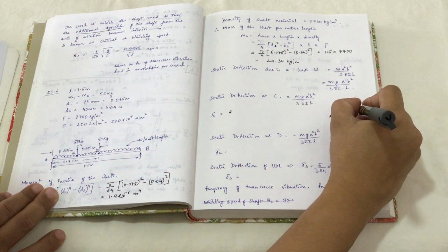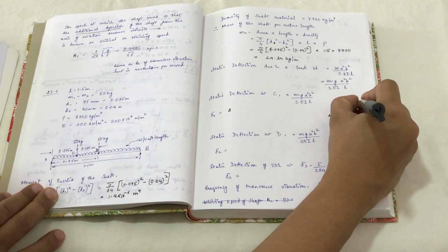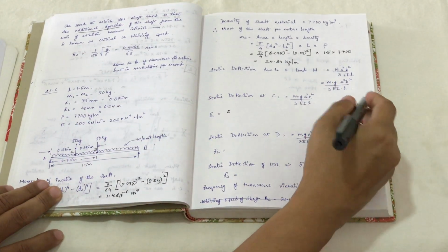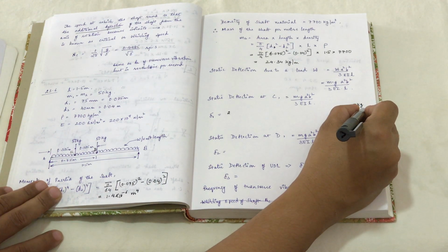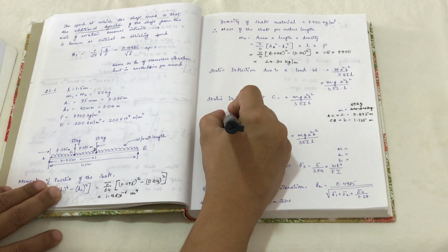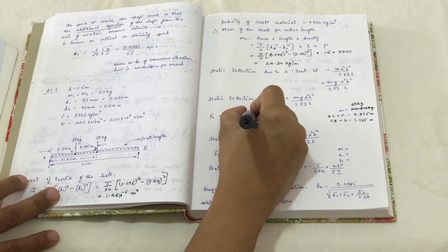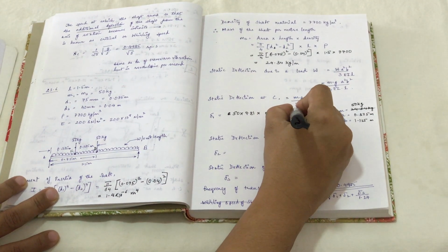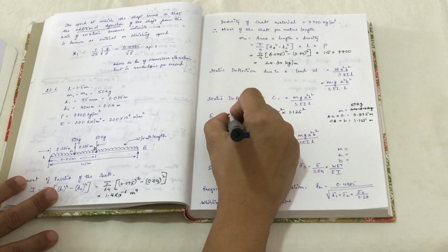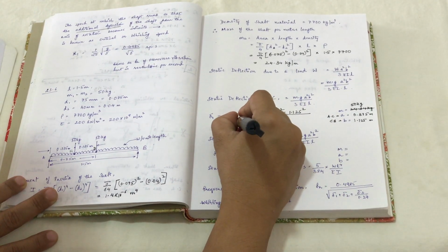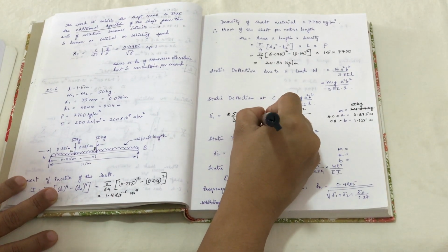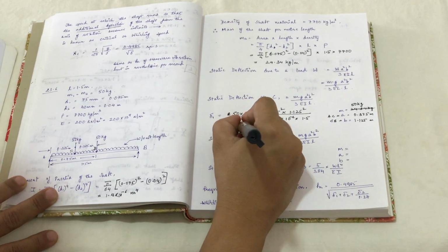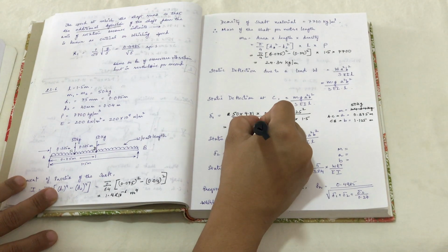Okay, so this is not 24.3, it should be 50 kg, because we are taking the mass of the first load, that is a point load. This 24.3 is for the uniformly distributed load, that is the weight of the shaft. So please take it as 50. So 50 multiplied by 9.81 multiplied by 0.375 square, 1.125 square divided by, the rest remains the same, 1.4, and the length is 1.5. So if you calculate this, you will get 70 into 10 power minus 6 meters.